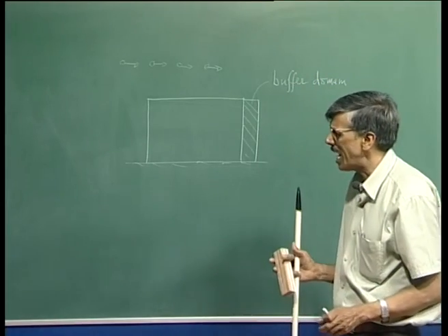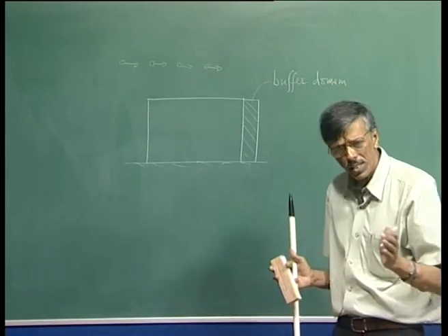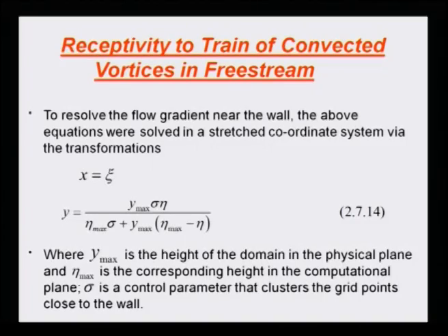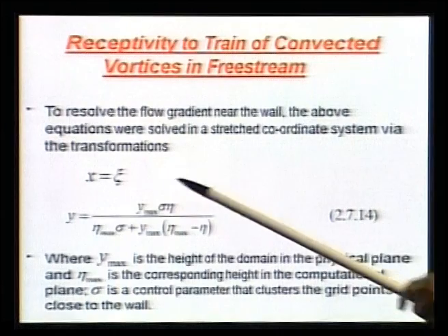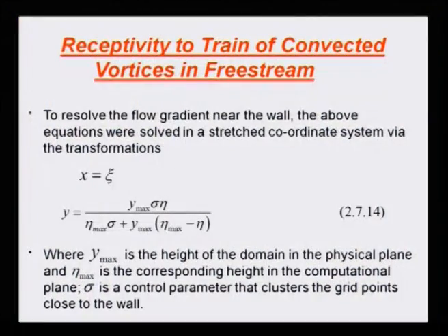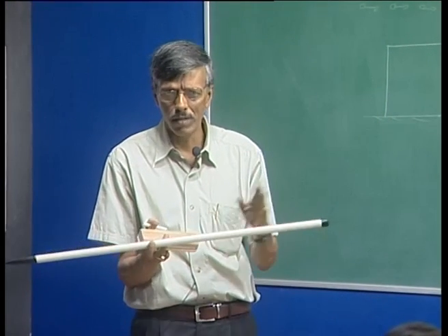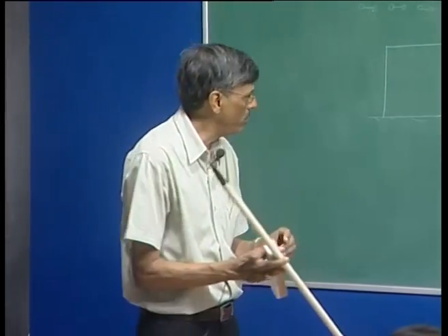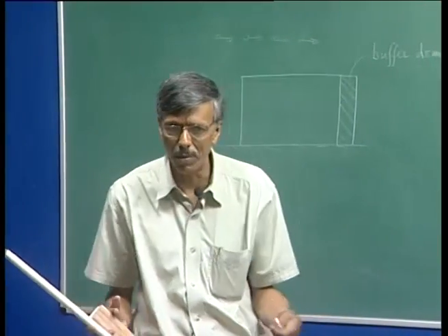If we are going to see that, then in the progression of that packet, we would not like to have anything other than uniform spacing in the streamwise direction, because there is no preference in the x direction. Because if I have a grid at that point, sometimes a vortex will move past, sometimes it will be free, but we do not want to do a fancy time dependent grid.